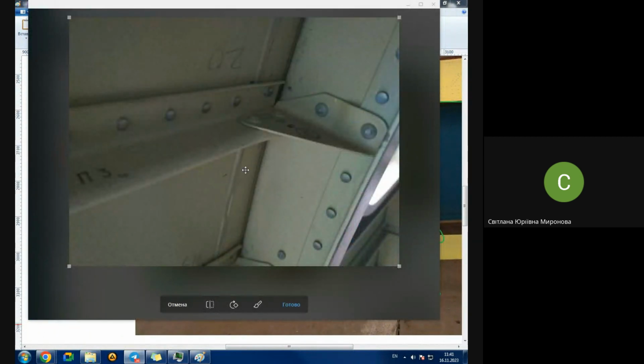No, besides the knee, what is visible here? And besides the end of the stringer, the beginning of the frame, look at this, please. What do you see here? Really, in cross section, at this place they have one skin, and it goes along. And here they have one more skin. It's a so-called doubling plate. There are two skins here. It's the thickness of another skin, and this place is covered with hermetic sealant.